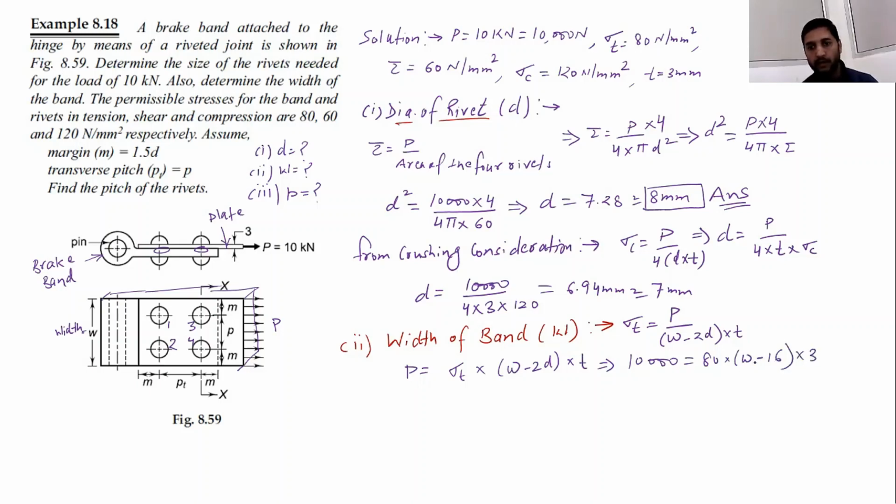So देखिए इस equation में there is only one unknown now, which is W. So width from here, when you will solve this equation, you will get the value of W, that is width of the band, as 57.67. Okay, and approximately equal to, let us say, 58 mm. And in our textbook इन्होंने round किया है 60 mm. ठीक है ना, तो you can round it as 58 mm also. Both are correct. Okay, in our textbook they are taking the standard values.